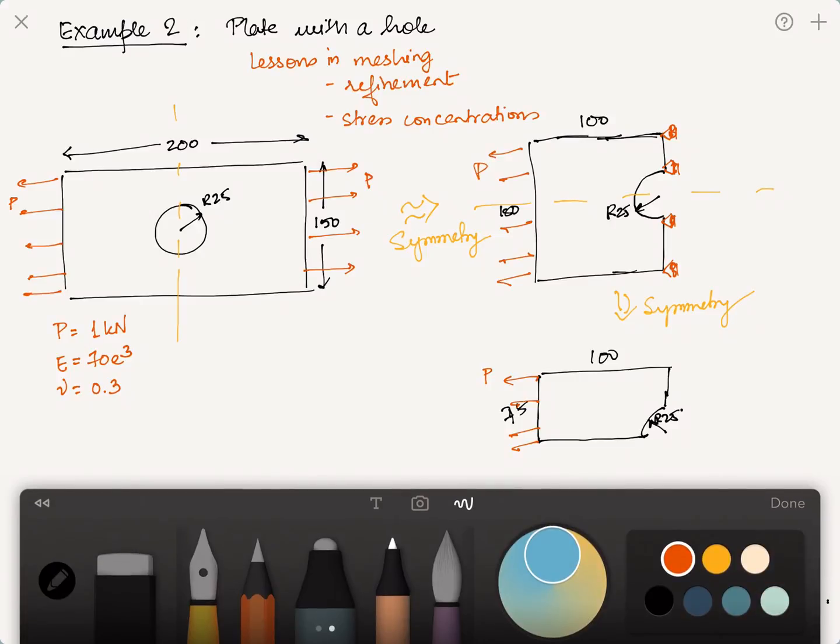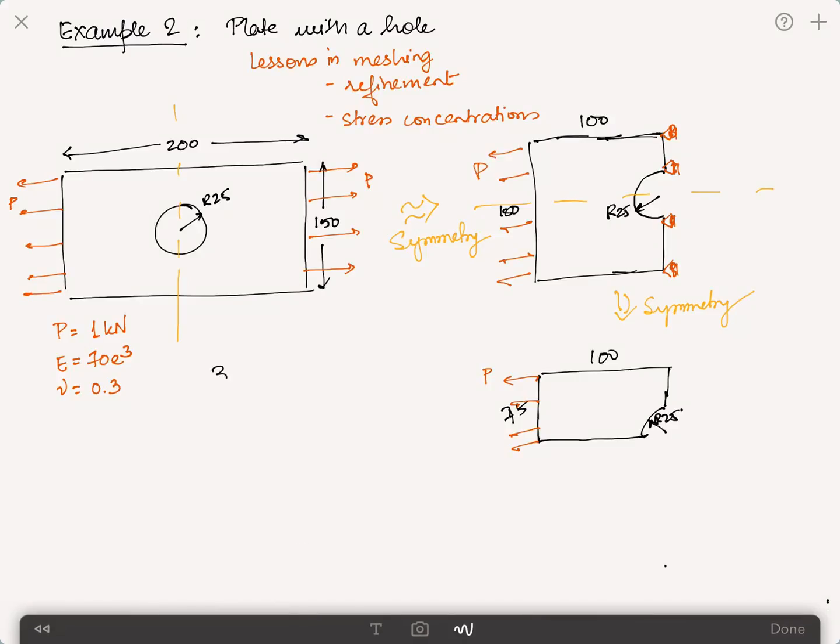Now there we are going to use 2 kinds of elements to model it. One would be 3 node triangular elements and 4 node rectangular elements. You can of course also use a combination of these 2 kinds of elements. I can already give you a little hint. Triangular elements are much stiffer. We'll study about them, so we try to avoid using them as compared to rectangular elements. Now over to Abaqus.